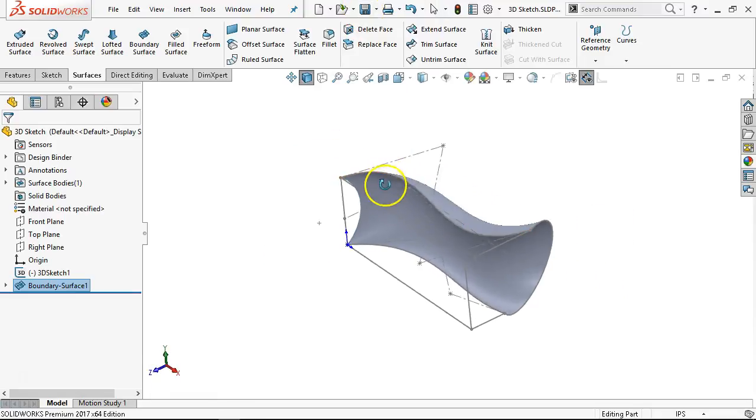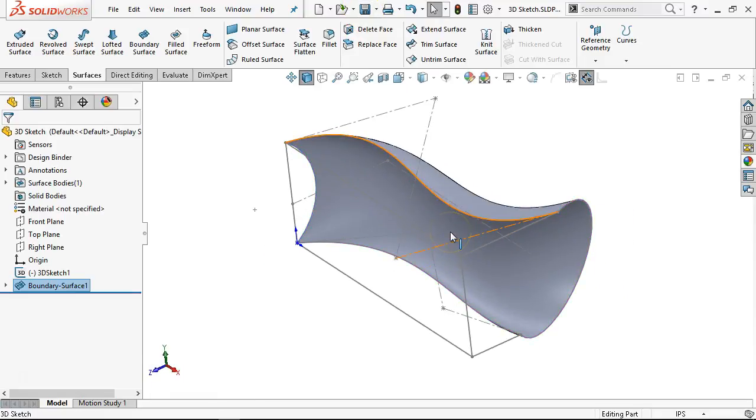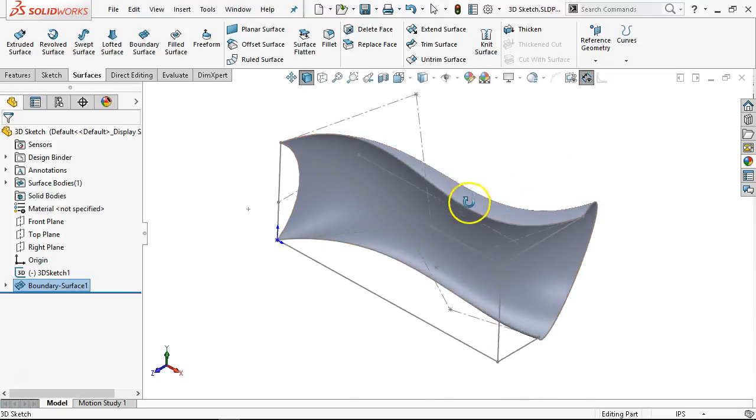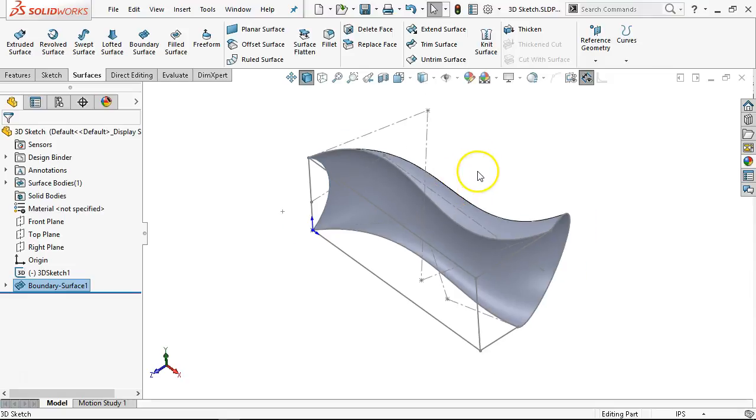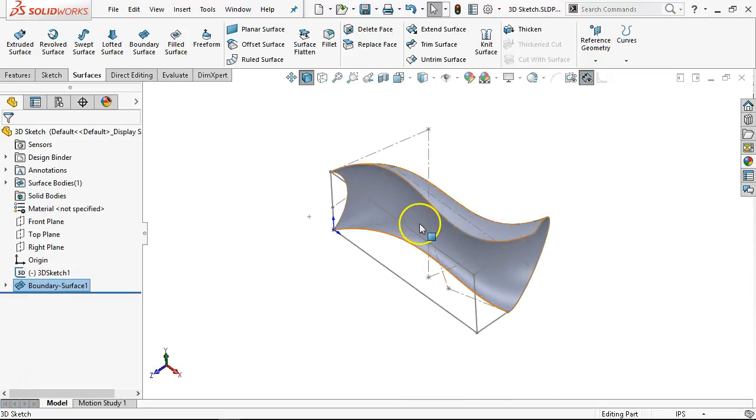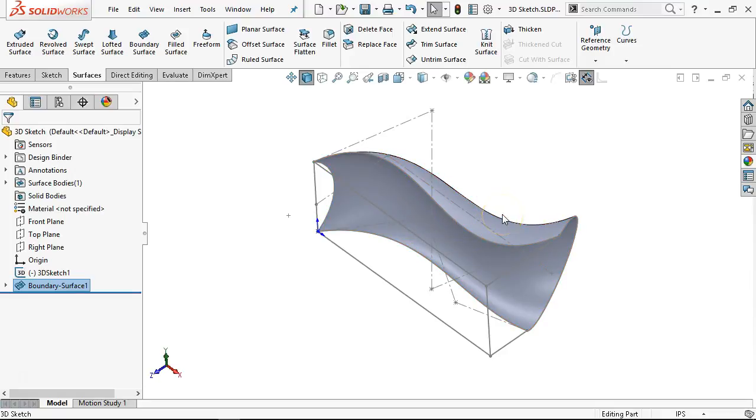All right. So the biggest problem with the surfaces is visualizing the construction. What is going to give you the resulting geometry? And it ends up with the 3D sketches, transitions, curves, combinations of sweeps, lofts. You're not limited to one tool. You're going to have to combine up to get a decent result. All right, so we'll save the more than one loft section boundary to the solids.